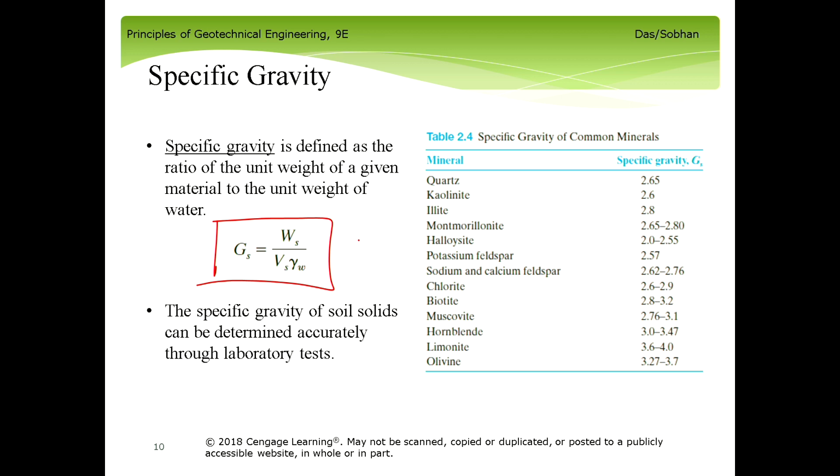So people use the weight of water compared with other material to calculate the material weight. This is why in here we use specific gravity. So for a fixed material, it has its own specific gravity. For soil, it's usually around 2.7. It ranges from 2.6 to 2.8, but usually around 2.7 for most soil. Yeah, it lists in here.